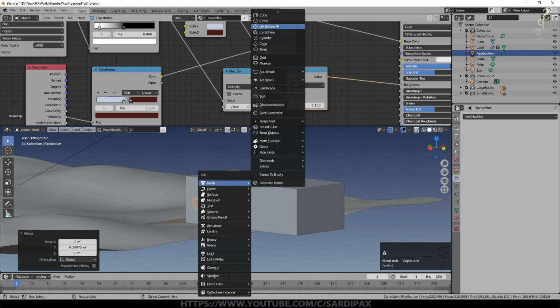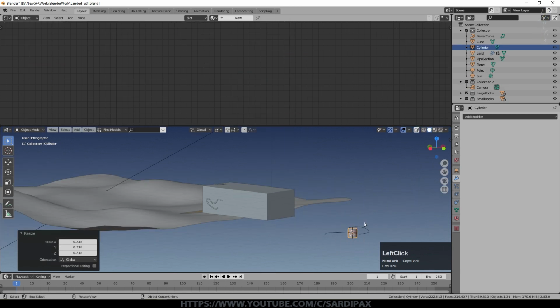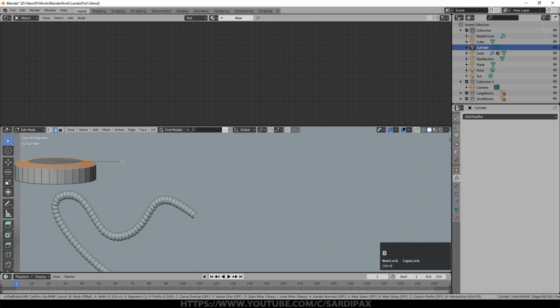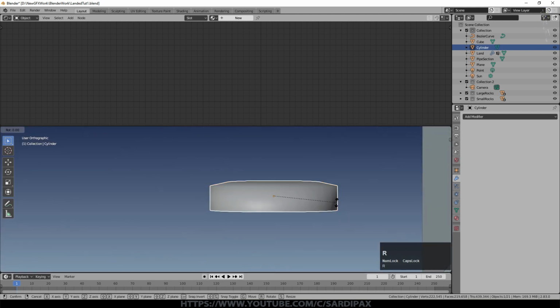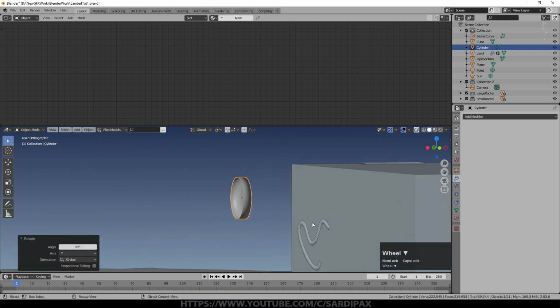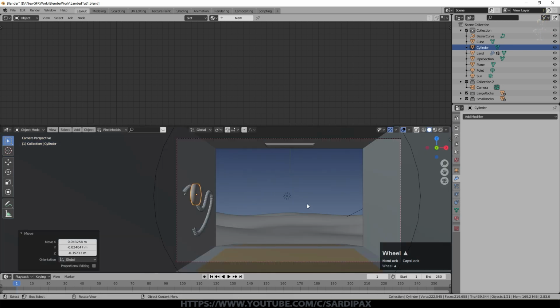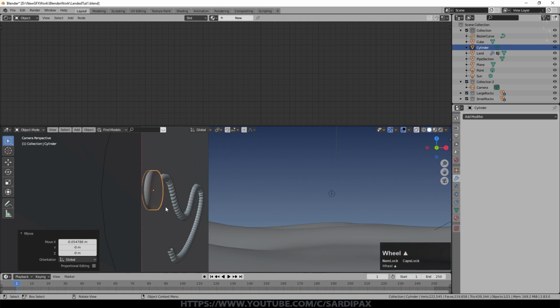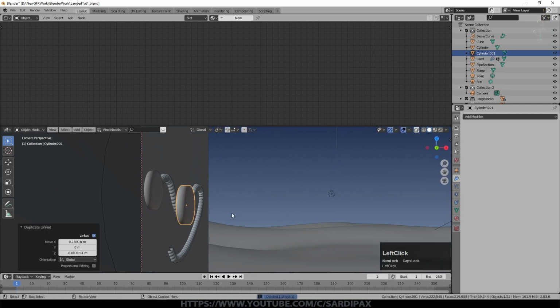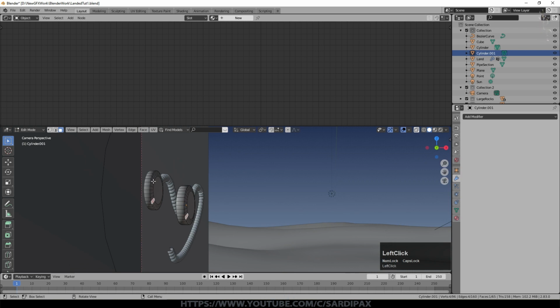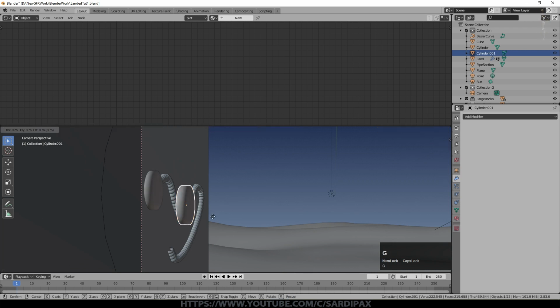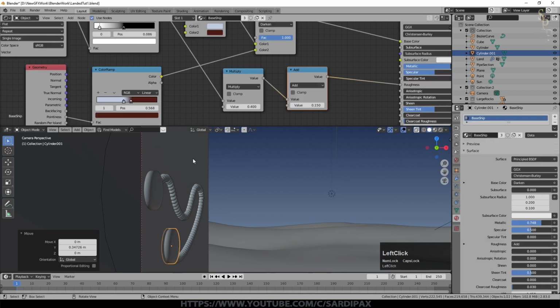You can also add perhaps a small cylinder, add a little bevel to the top, set it to shade smooth, take away the face at the bottom, rotate Y 90 and G X. And I used that just to cover the ends of the pipes. And if you do Alt D, if you make any modifications to one, you can see it's going to affect both of them, which can be handy if you want them all to be the same. And we'll select the ship base material.